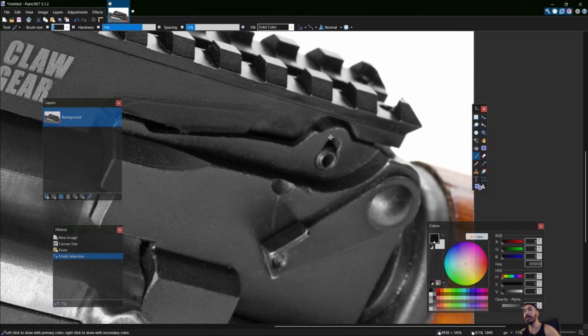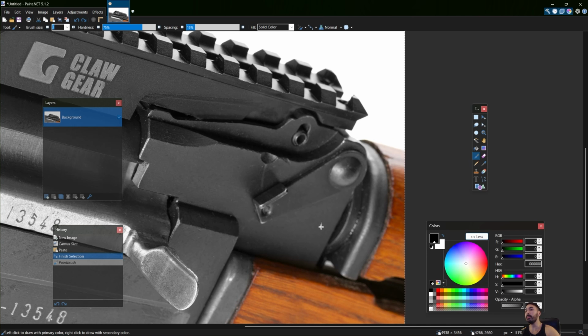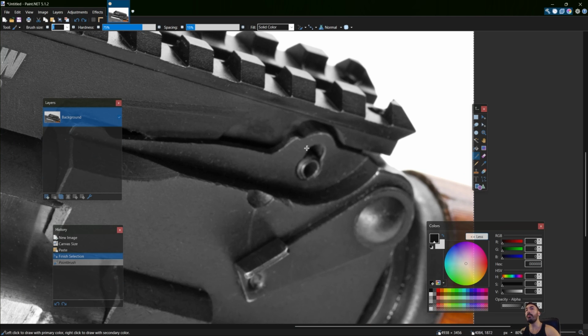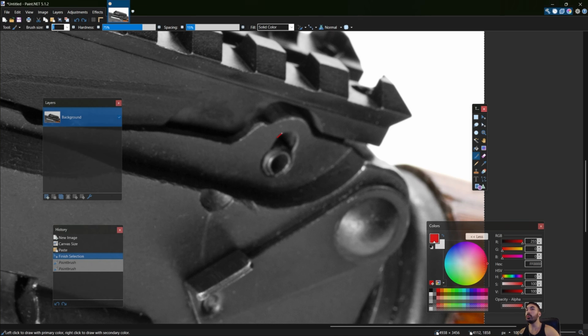So for example, in this case, that's going to be this little hole over here. All the other parts are relatively simple shapes, at least on the main block here, but this is something where we're going to need very specific geometry. So I already know that I'm going to use a semicircle up here and then a little straight line, which is going to consist of a few edges. The question is, how many edges do we want to have on this semicircle? That's going to dictate how many edges we have on the full circle.